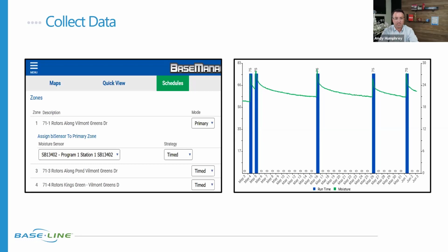Right. And so during the initial installation and configuration, it's highly recommended. And if you're a specifier watching, it might be good to put in your spec documents for the contractor to make the sensor assignment so that when we're ready to automate, the sensor has been assigned to the correct zone and it's ready to basically flip the switch to automation. We don't have to go back and look for the design notes and figure out what's the serial number, where is it located, what zone is it in, all of those things. That can be done right at the time of installation.